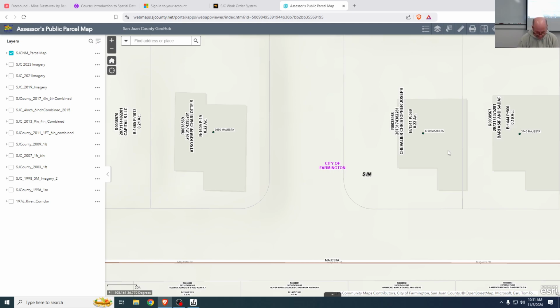Okay, so that is mostly west of the Mississippi, and we talked about that, where east of the Mississippi, they used a slightly different method called metes and bounds, which is short for measures and boundaries. So they would use more descriptive descriptions of road boundaries, physical or natural boundaries. The chapter does include those principal meridians for the different township and range legal descriptions, the PLSS baselines and principal meridians.